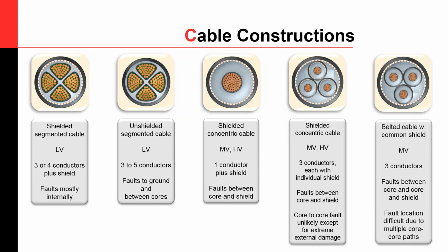And then on the right, you can see the dominant type of construction for PILC cables, from when cable installations were pretty much being conceived as electrical connections. So this is pretty much the oldest way of constructing a cable. You have three conductors, but they only have one common shield. And that leads to certain problems.